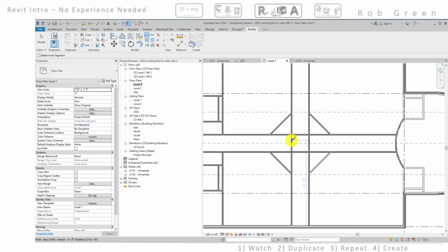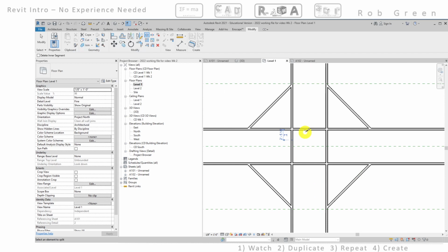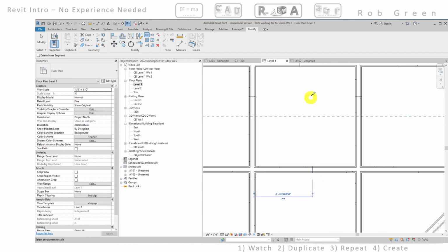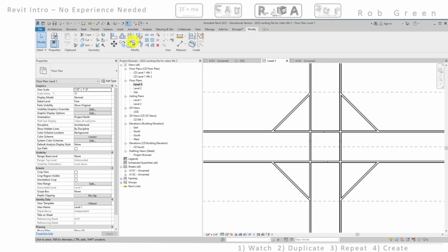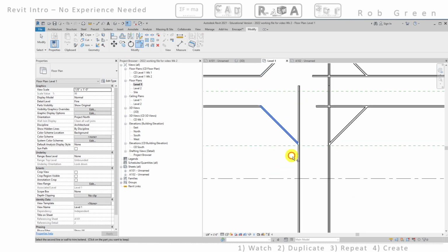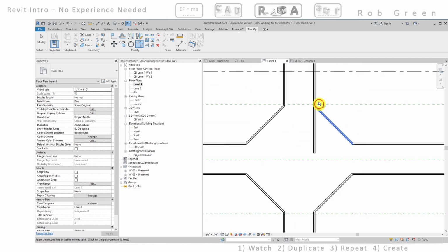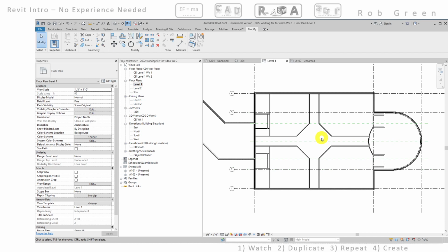And right, I get the X-Acto knife. So I'm going to click the vertical wall, the horizontal wall, vertical wall, horizontal wall. And if I were to zoom in really close, you can kind of see now there's a separator where I clicked. I hit escape a couple times. Notice now those walls are multiple pieces. So now if I use trim to a corner, I get that done, I get that done, and kind of going around the clock here. And I think we have a model that is relatively complete.